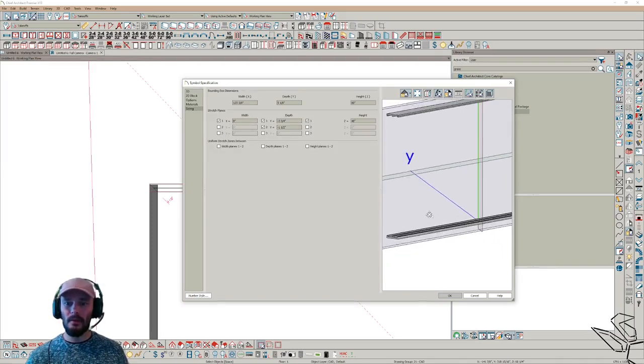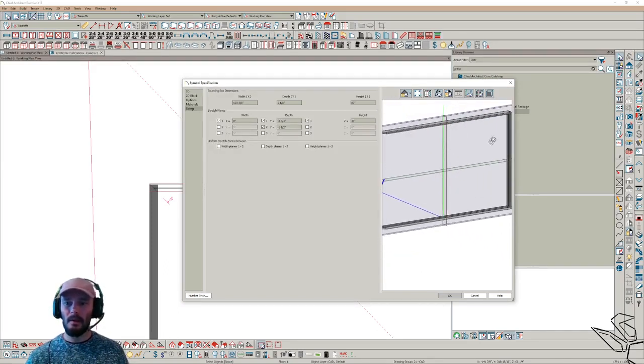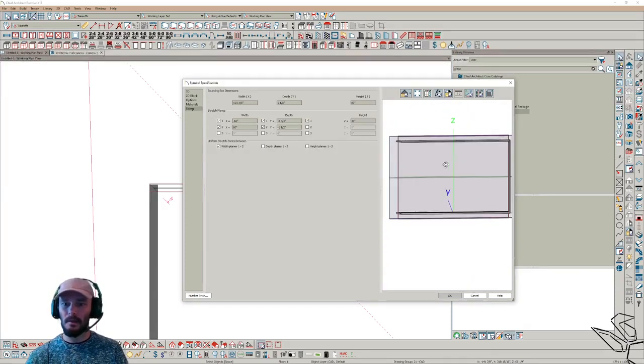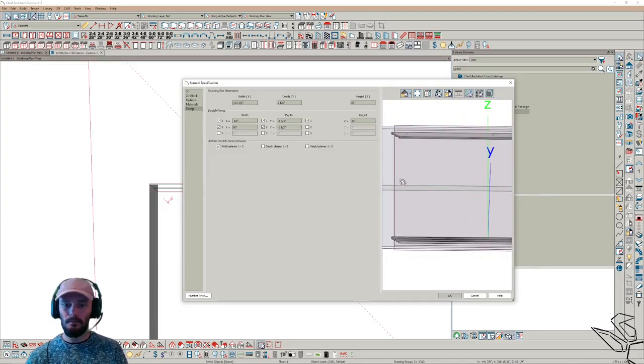This one, I want to stretch. I don't want to stretch about here because it will eventually stretch this frame. I want to stretch uniformly between 2 places. And 123 inches, so let's say we want to stretch in between 60 and -60 uniformly. So I got to check this width planes in between those two, right? So almost all the way up to the frame, it's going to stretch uniformly. I don't want to stretch this angle, so maybe 58. Oh, 56, 54. Why not? There we go. Perfect.